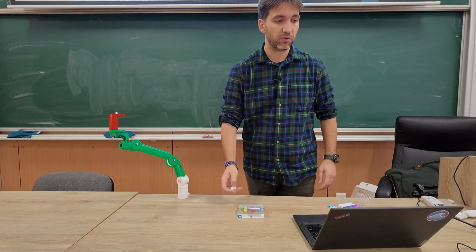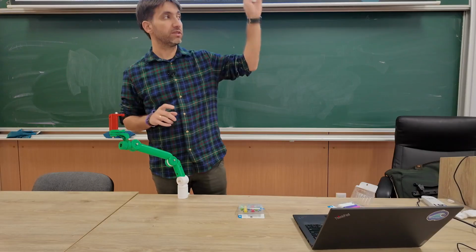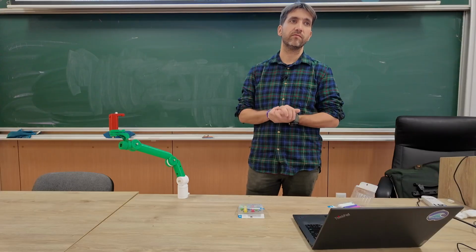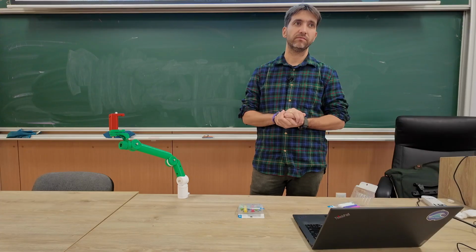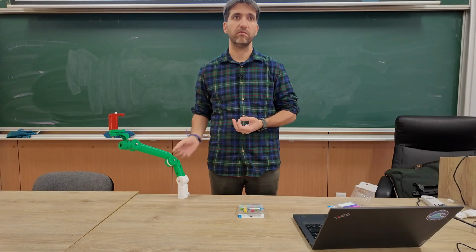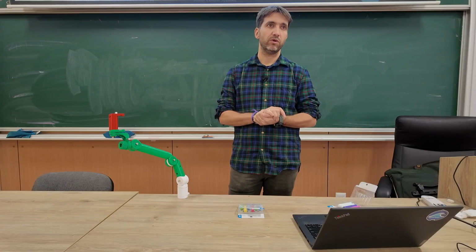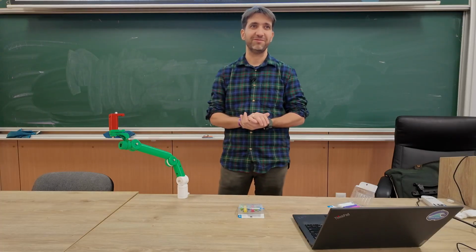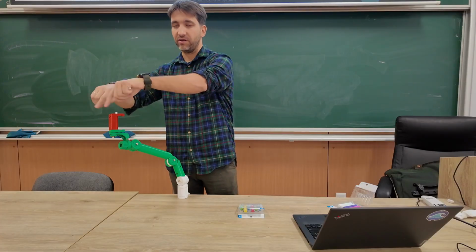Or would it be the same thing, trying to control the end effector pose in this kind of scheme, or the joint positions? I think the end effector pose is harder to measure than joint coordinates, because joint coordinates, I think they can be measured with encoders. All right. And for the end effector pose, I have to have some system that can tell me the pose in 3D space. Which we know. How do we do it? Forward kinematics, right? If I know joint coordinates, I know where the end effector is.